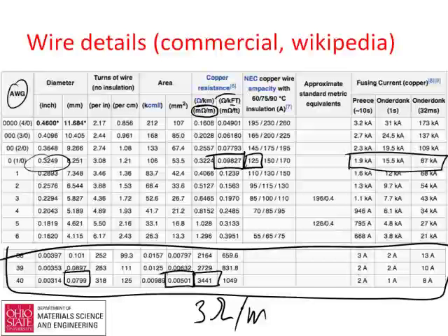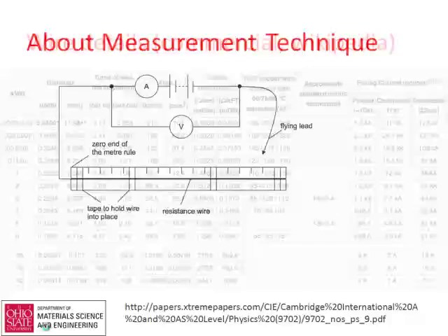So we can use this fine copper wire. Be careful not to put too much juice through it, because at 2 amps in about 10 seconds you're going to end up melting the wire. But that's actually a good thing. It limits what your students can do with it. So even with copper, you can do that. Or you can change to stainless steel or other things that have higher intrinsic resistances. Again, 40 gauge copper wire. I've got a big spool, very happy to share. I think $20 buys you about a mile or two of wire. A little money goes a long way with that.